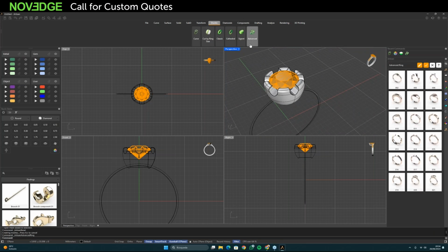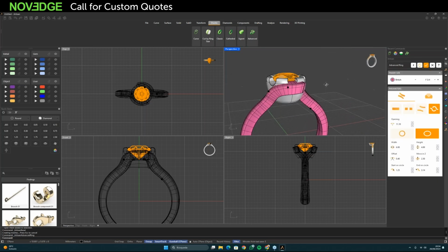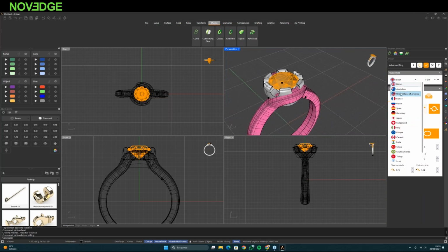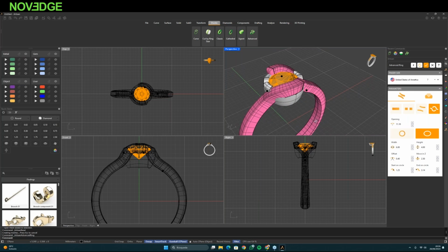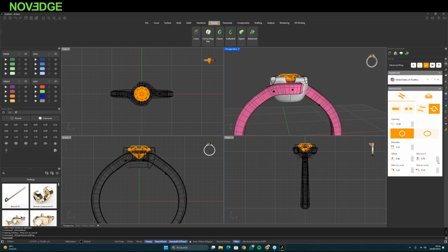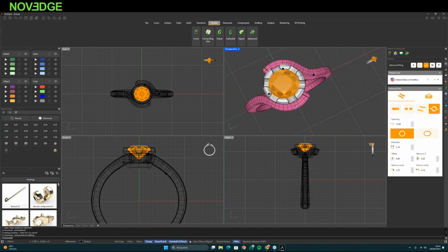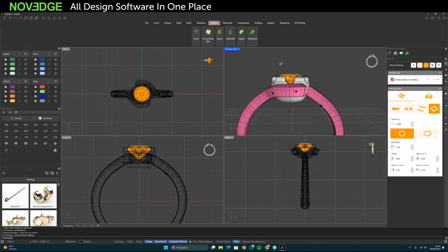We go to the advanced rings, and I'm going to select this and edit it to adjust it to the stone that we have. Let's set the size. And from here, I'm going to modify all the settings. So this is going to be 13. It's round. First, I'm going to get down all of this. It's funny to see how it moves down this way. So I'm going to increase the offset. Something like this. So it seems that it embraces the bezel.